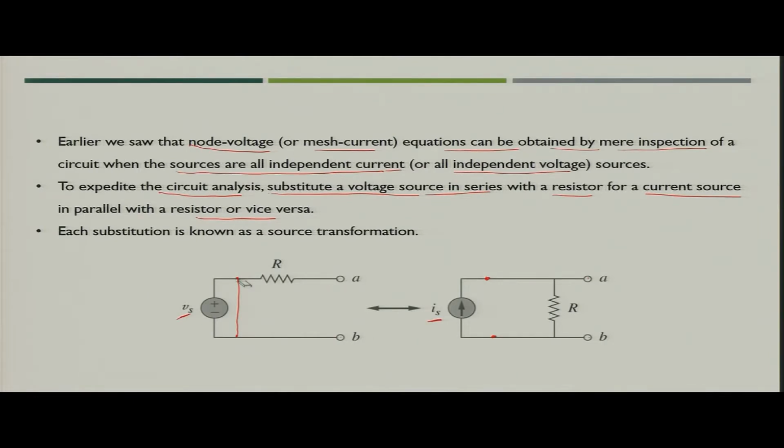The circuit is same as it was previous, the thing which you have to do now is that you have to short circuit A and B, and your objective is to find out the value of this current, short circuit current. So, suppose if it is ISC, so what would be the value of ISC? ISC would be simply Vs by R.